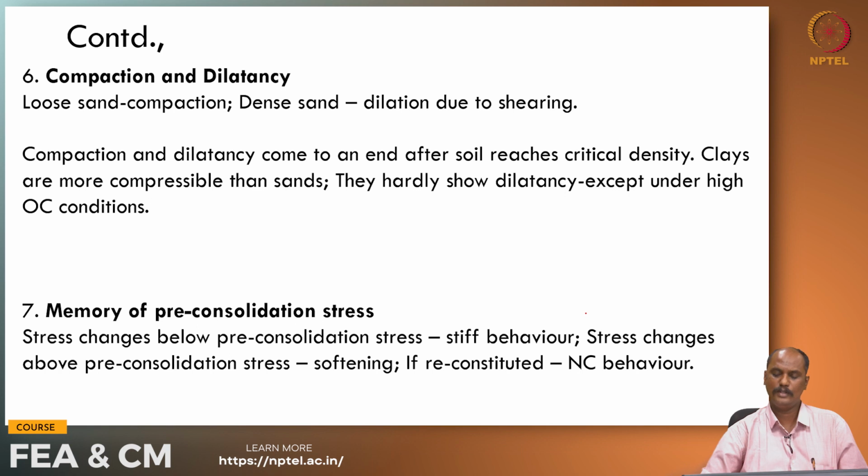What happens if the soil is reconstituted is that the memory of the soil is lost, or the pre-consolidation stress is erased. For example, in the case of normally consolidated clays, if the soil is reconstituted at 1.5 times the liquid limit, usually the pre-consolidation stress, or the memory of the soil, is lost. So, we can reconstitute it to rework on it.